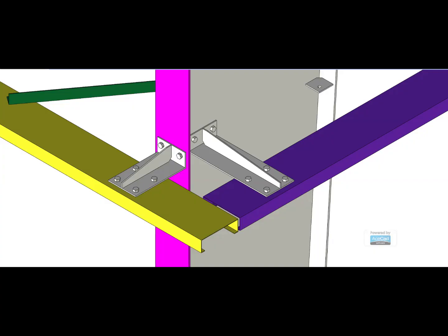When checking a connection, we should pay attention to the member orientation, supporting plate or cleat arrangement, bolt locations, and the relationship between the girt and the column. However, one important rule applies here. The exact connection arrangement must always be taken from the approved project connection detail. We should never assume bolt size, bolt quantity, plate thickness, or connection geometry simply because a similar connection was used on another project. The real drawing is the source of truth.